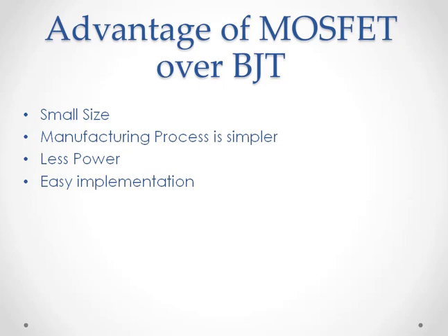silicon chip. Compared to BJTs, MOSFETs have more advantages. That is, MOSFETs can be made quite small, requiring a small area on the silicon IC chip, and their manufacturing process is relatively simple. The MOSFET operation requires comparatively little power, and circuit designers have found more ways to implement the digital and the analog functions utilizing MOSFETs exclusively, with very few or no resistors.